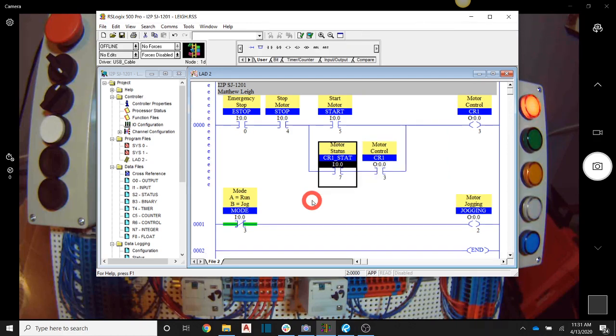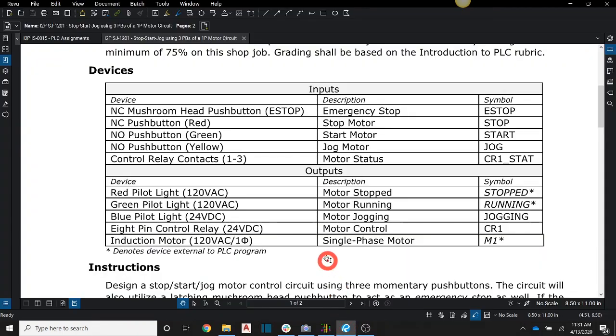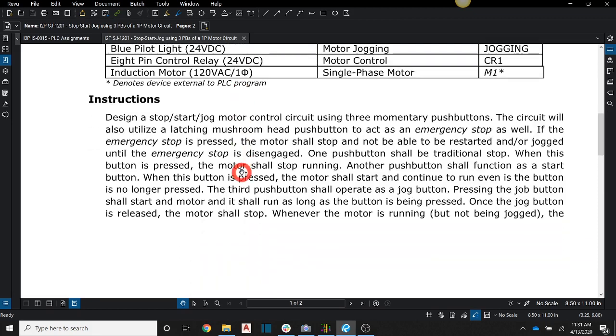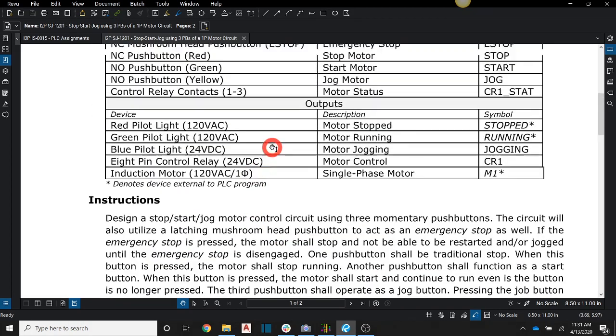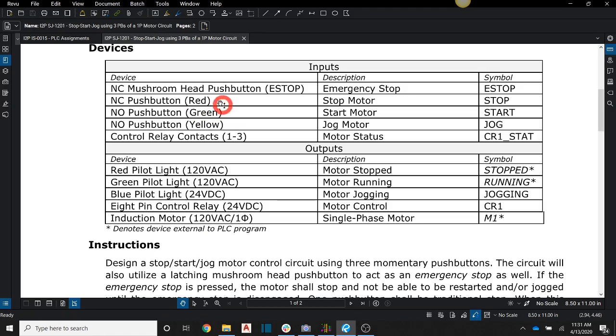Okay, so we have our start stop station like we had for 901 right here, correct? So that is what we need if we push the start button, is what by definition over here is what we need when you read the description. We need, if we have the green button pushed, it's going to be a normal stop start station. What we need now is this yellow push button to actually be a jog function.